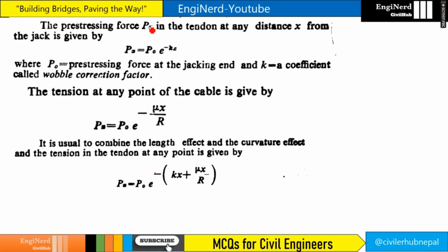If you see the loss due to length effect, the pre-stressing force Px in the tendon at any distance x from the jack is given by this formula: P naught e to the minus Kx, right? So P naught is the pre-stressing force at the jacking end, and K is a coefficient called the wobble correction factor. This is Kx, and this is Px. The tension at any point of the cable is given by...